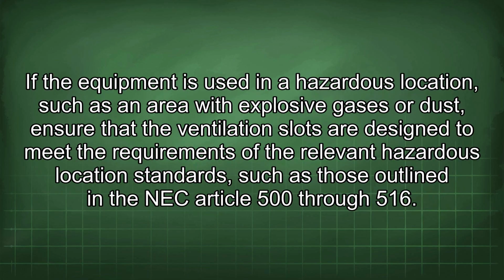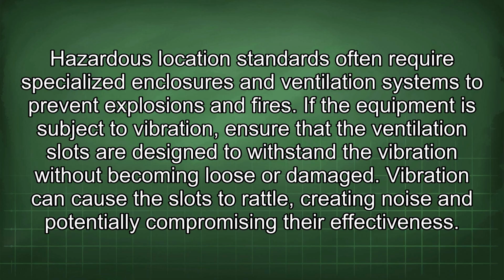If the equipment is used in a hazardous location, such as an area with explosive gases or dust, ensure that the ventilation slots are designed to meet the requirements of the relevant hazardous location standards, such as those outlined in the NEC Article 500 through 516. Hazardous location standards often require specialized enclosures and ventilation systems to prevent explosions and fires.